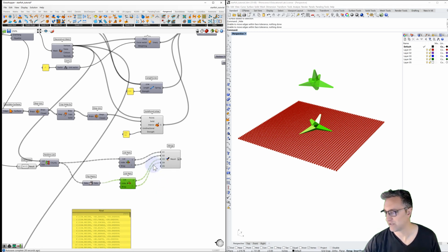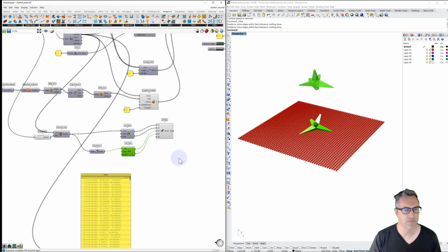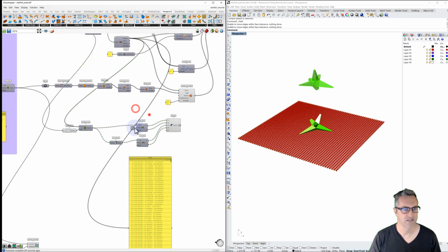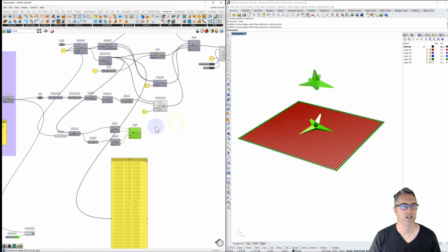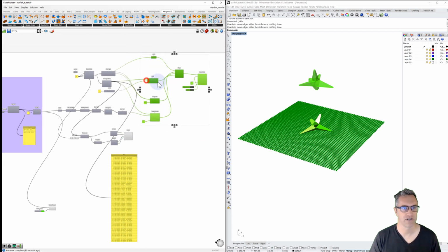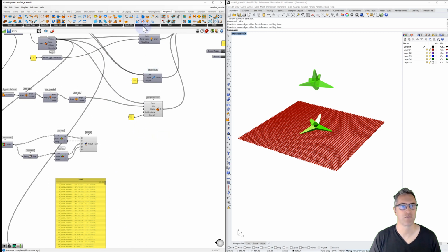So the last thing that we'll do is plug these in and create these as anchors. It's a little bit of setup. I want to move these over. Like I said, I've been trying to get these elements to line up so that now our Kangaroo elements will all line up. And so under goals for points, we want to grab the anchor.